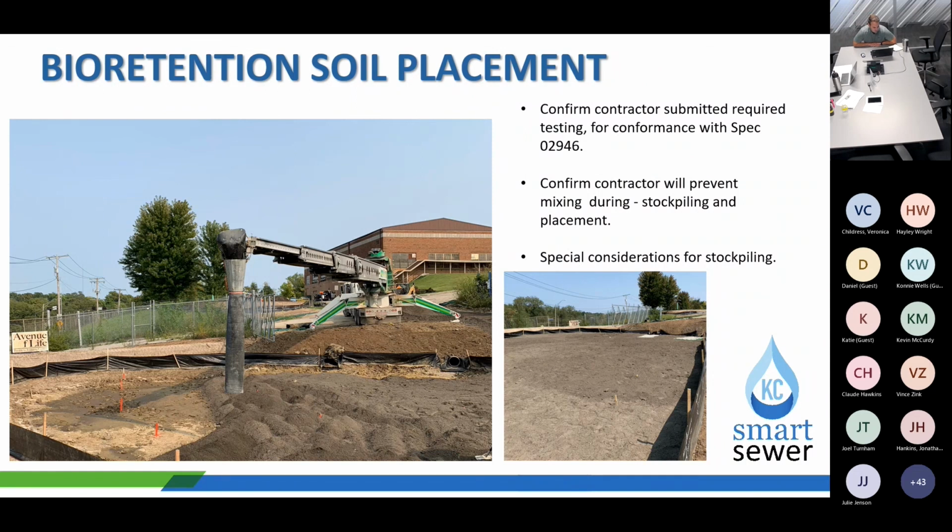Bioretention soil placement. Again, confirm the contractor submitted the required testing and it's an approved material that is brought to the site. This stuff's kind of difficult to get, honestly. So just make sure that the tickets delivered to the site with each load match the approved submittals. Also confirm during unloading and placement that the contractor is not mixing the BMP soil with any other native soil. It's very important that they keep this clean of any debris or native soil as it's being placed.